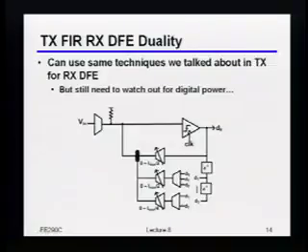Because in this particular example, even though I can cover a pretty wide range of coefficients, I'm only paying something like 1.25x of this peak value in terms of parasitic capacitance, right? So, just as a reminder, this picture that I'm drawing here was exactly the picture I drew at the transmitter. I've just folded it to now be in the DFE feedback at the receive side, okay? So all the tricks that we talked about for how you build FIR filters and minimize parasitic cap at the output node, all of that stuff directly applies to the DFE as well, okay?